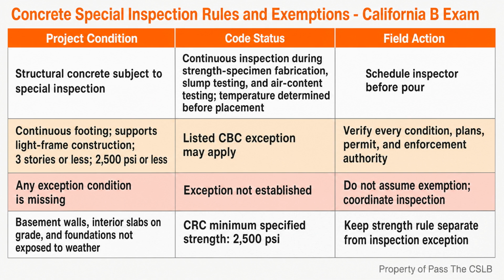This is where the phrase "do not water it down" becomes useful, but I use it carefully. The point is not that water can never be added under any circumstance. The point is that field water is a controlled mix change. It must remain within the approved mix limits and follow the required authorization and record keeping. A hose is not a design tool.